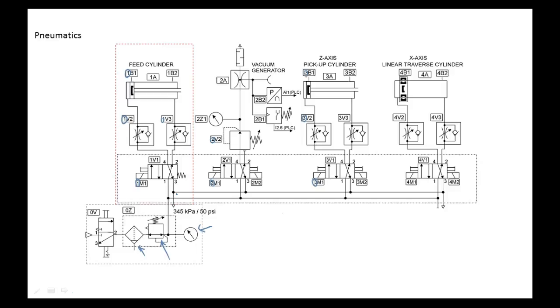I mean, for the most part, though, isn't 4 pretty consistent? No, well, it depends. It depends on the number of positions, and of course, how many exhausts does it have? Most of the time, when you got like a 3-way valve, you have 2 exhausts on each end. If they combine the exhausts, then usually it would drop off. I never saw one more than 4 or 5. So if it's got an extra exhaust, it could be a 5-port valve, and it would have 1 exhaust per outside. Is the way this works.